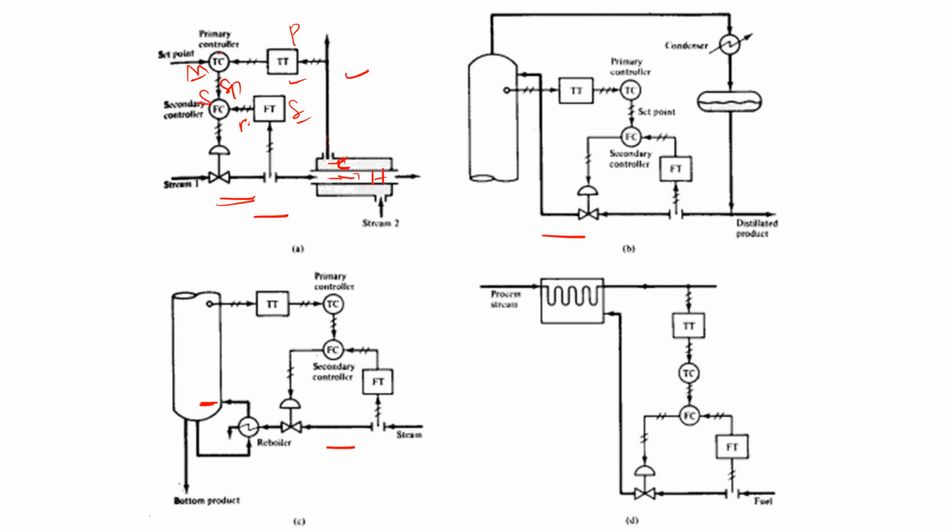Okay, the next one is the distillation column. In a distillation column, you have perforated plates, plates like this. So how it works is, here you have to give a feed, and then the vapor goes up, and then the liquid comes down. So this is liquid, this is vapor. So we can collect the vapor and condense it. When you condense it, it becomes liquid, and then that liquid is once again fed here. Okay, so likewise this process keeps on continuing. That is, this is vapor.